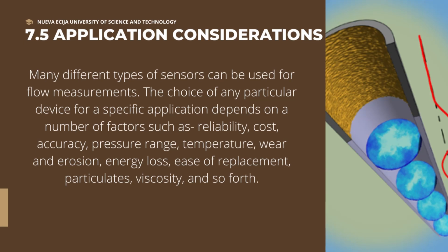Many different types of sensors can be used for flow measurements. The choice of any particular device for a specific application depends on a number of factors such as reliability, cost, accuracy, pressure range, temperature, wear and erosion, energy loss, ease of replacement, particulates, viscosity, and so forth.